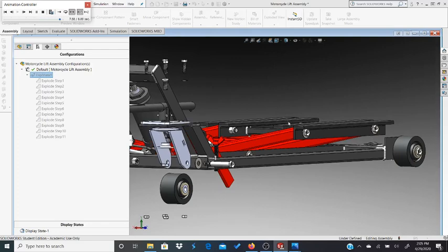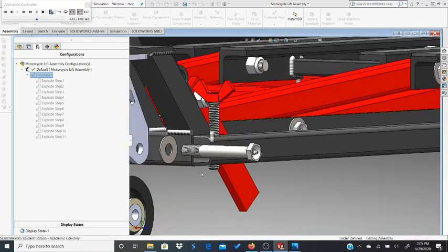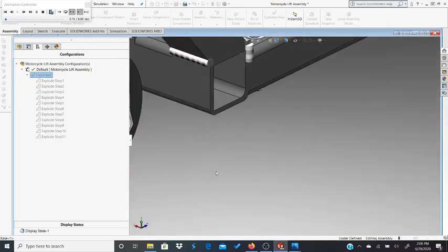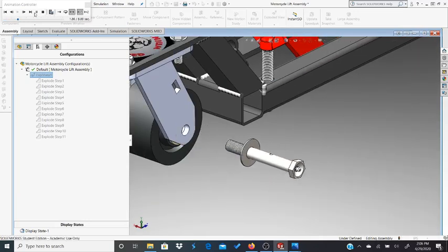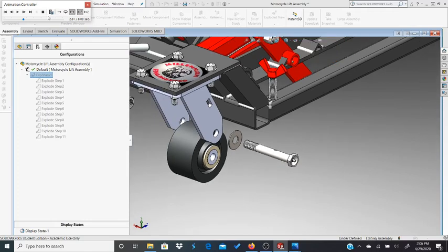I was able to find these on McMaster-Carr. I had to add the grease fitting in myself. You may be able to see it. Yeah, so you pump grease into this grease fitting. It pushes through a passageway here and then spreads out within this shaft. So as this wheel's spinning, grease will spread itself all over this smooth face. Let's collapse that.